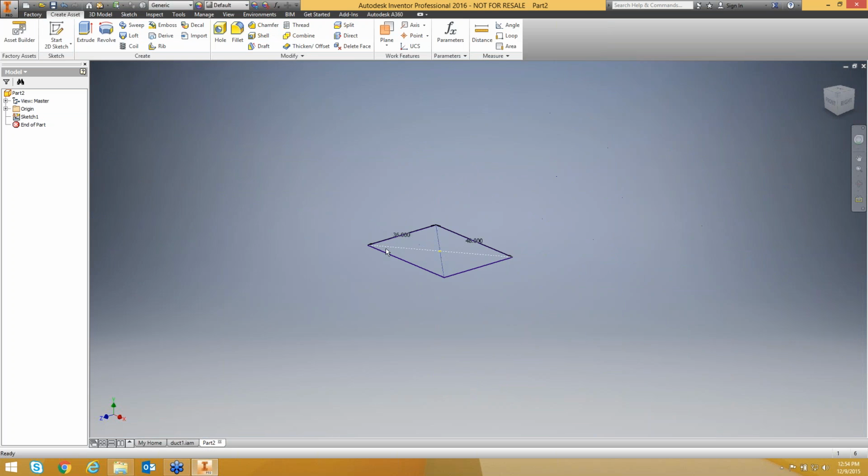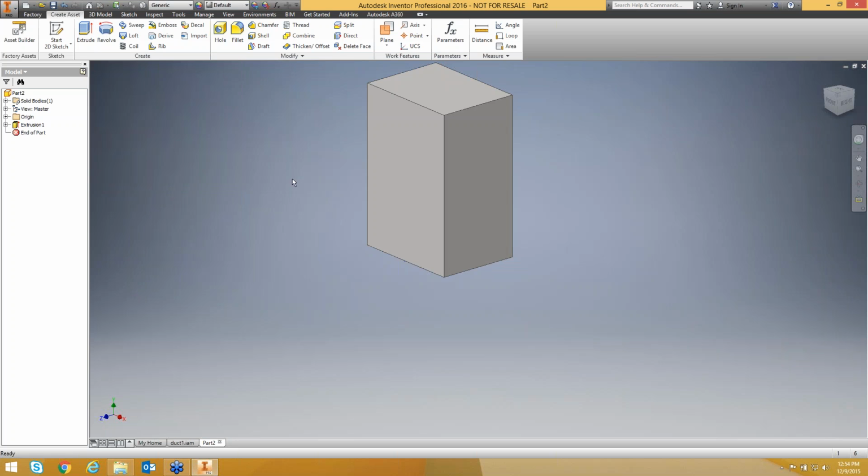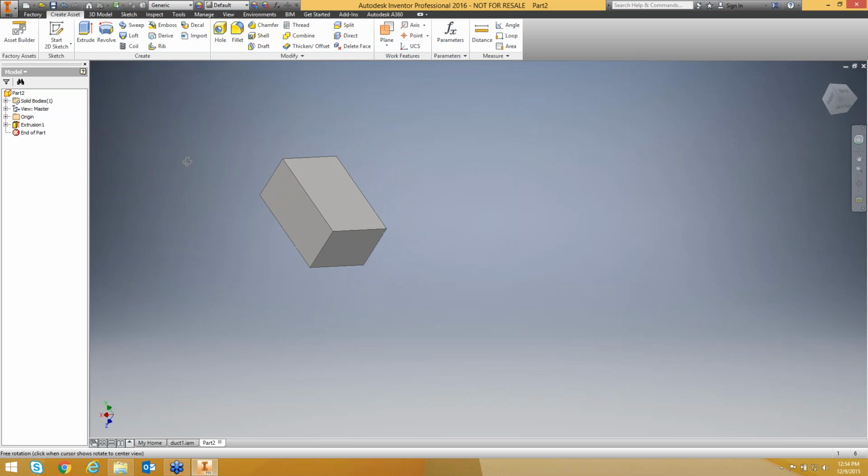Kind of typical Inventor, it likes to throw the screen around a little bit. I'll do an extrusion now. Give myself a good stretch here. This would be something where you might look at the manufacturer and see what they're going to be able to give you. So in this case, I might say 6 foot lengths. So I'll do my tick mark there to get all the way to the 6 foot. I'll say that's good now at this point.